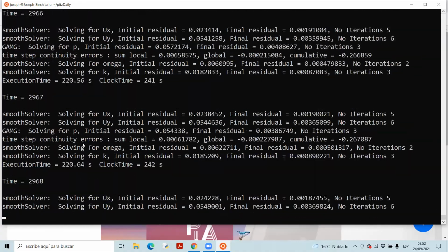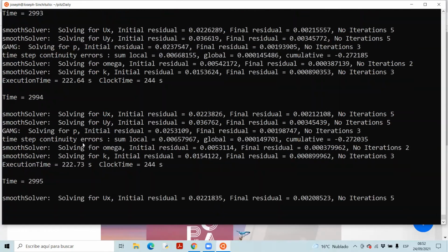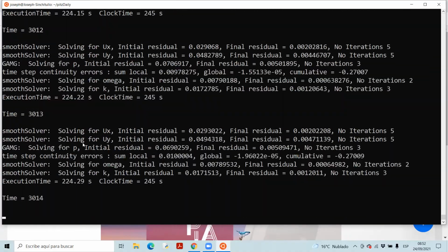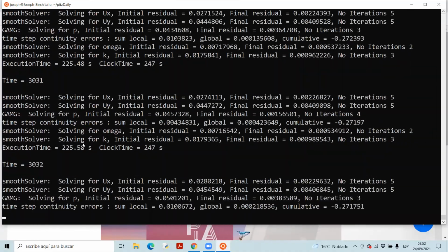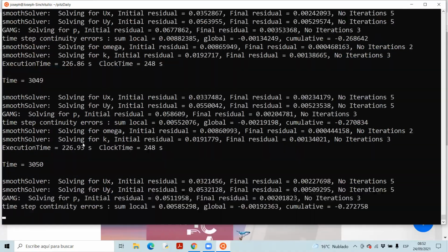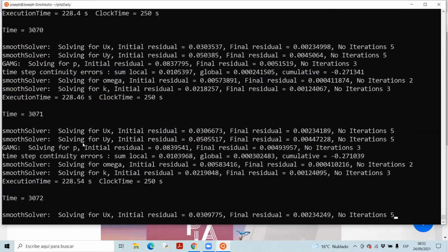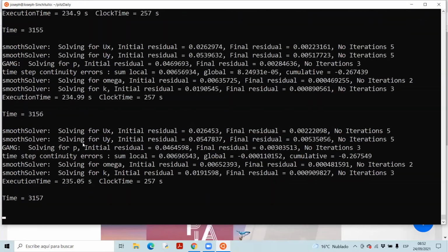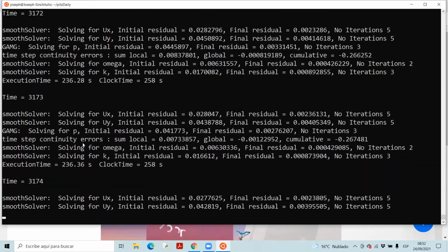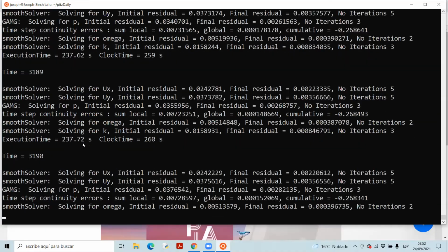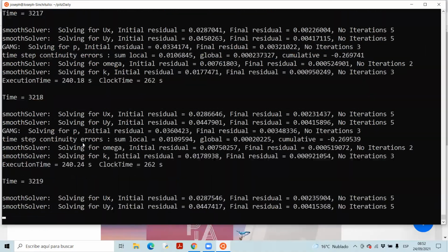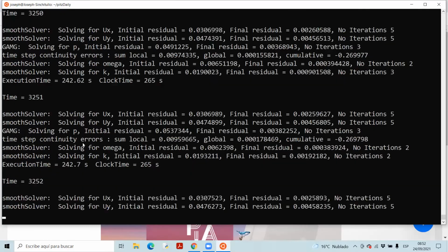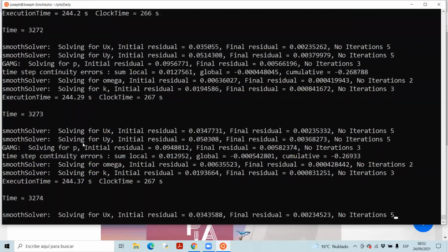In most cases, students have this problem because OpenFOAM automatically writes so many steps, and it will create problems. Most people use SSD. SSD is a solid state drive. These drives have only 238 or 256 GB of space. In that case, it causes problems. While if you have a hard disk of around 2 terabytes, it will not affect your system.